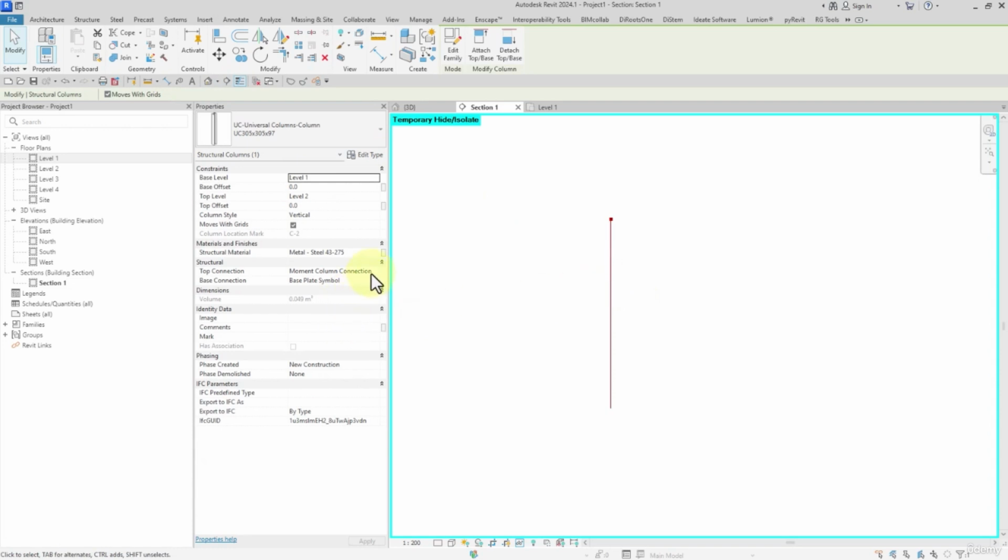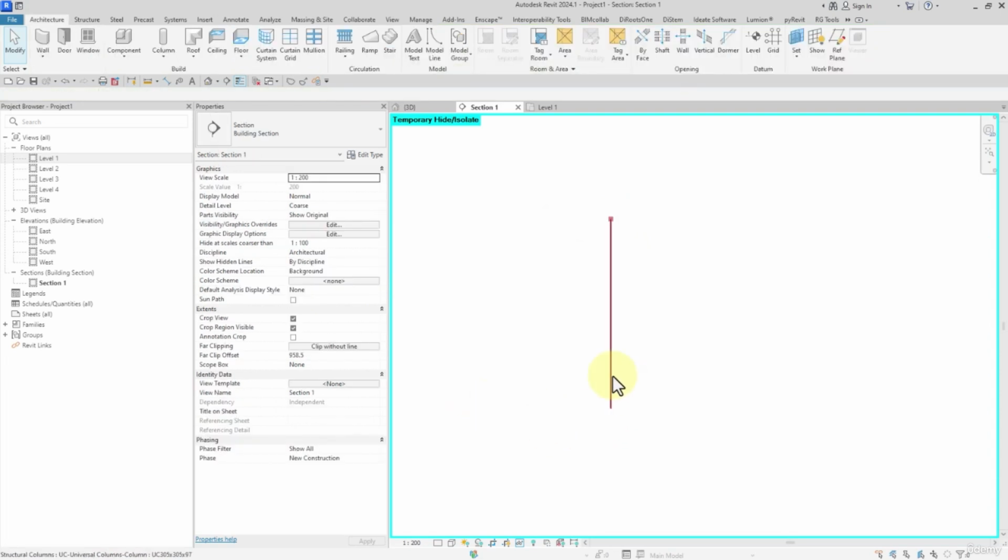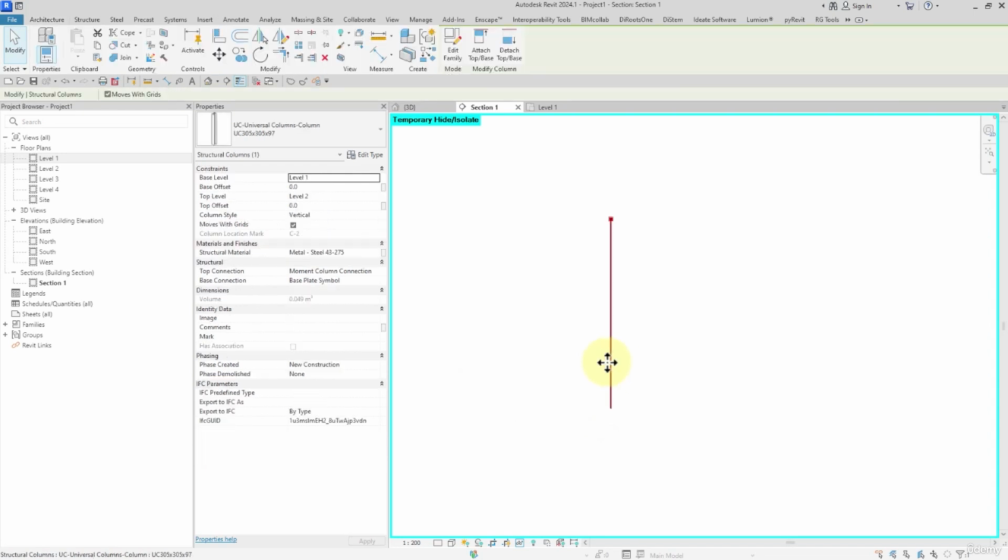Again, I select. And right now, since we are working in the floor plan level, we don't have access to the symbols. But we can create the symbols in the family environment and then replace them here. But note that we will talk about the connections and the symbols. However, we have instructed them comprehensively in our Revit structure course.